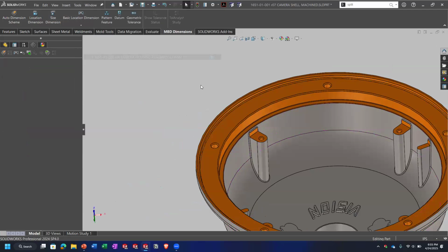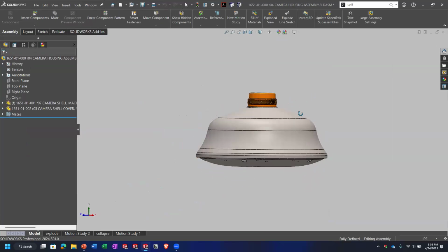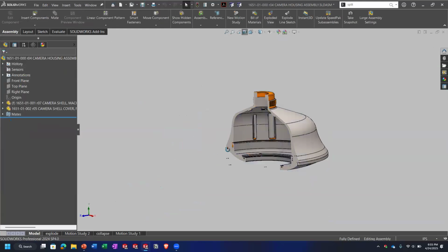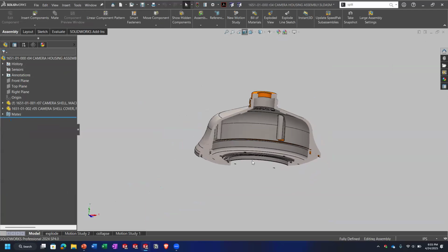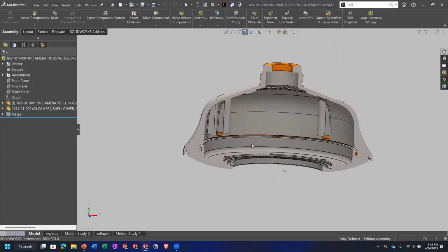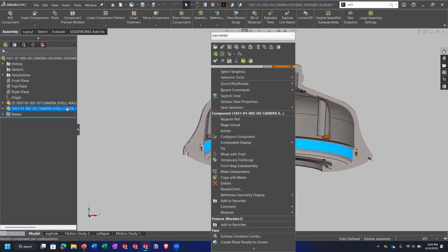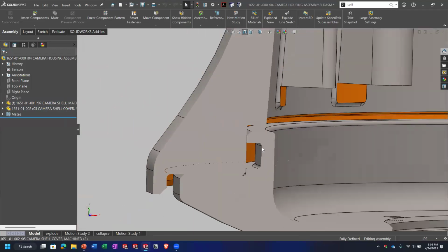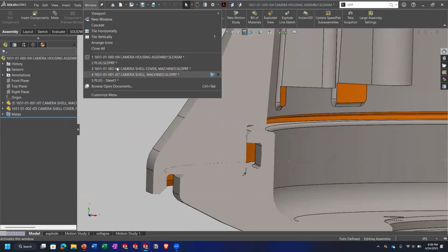So I'm going to do a quick manual dimension and tolerance stack up on this. This is a camera housing, like a heavy duty cast and machined camera housing for wash down environments that we help design. Tolerances are pretty tight because everything's waterproof and O-rings and all kinds of stuff. So there's more features on here, but I'm going to simplify things and we'll just look at fit between these two parts. I want to basically make sure that this slip fit is going to be a slip fit. So I want to make sure we tolerance that correctly.